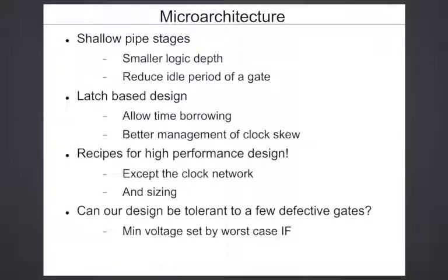But just because you are doing time borrowing doesn't mean that there will be glitching. One doesn't follow the other. Your statement that imbalanced delays lead to glitches is correct. But why should having a transparent window lead to glitching? I could have a transparent window, but maybe only one signal, the final gate feeding into the latch, just fires a little later. So with the transparent window, you are able to still capture it.